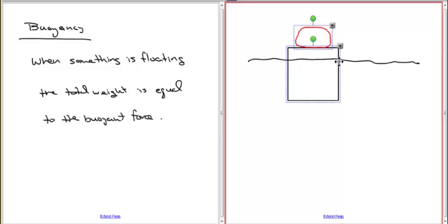And you can figure out how much this thing is underwater by finding out how much weight we have here, which is the mass of each thing times acceleration due to gravity. And if this thing has a consistent profile as it goes down, you just take the area profile multiplied by this height, and you can figure out how much volume is displaced.